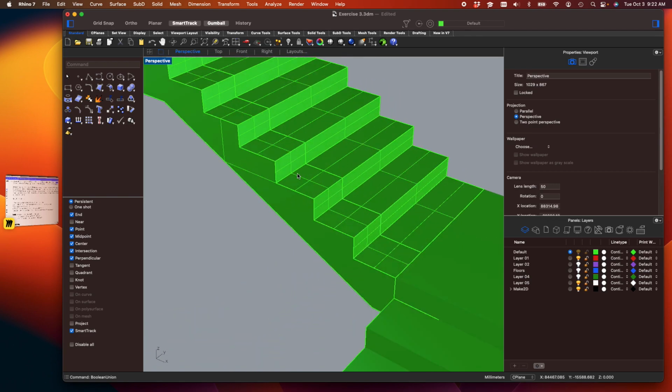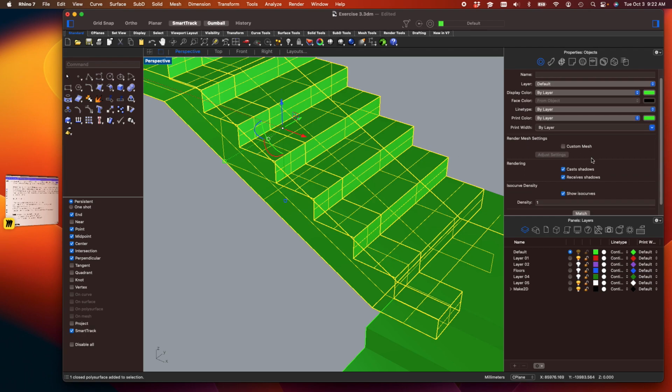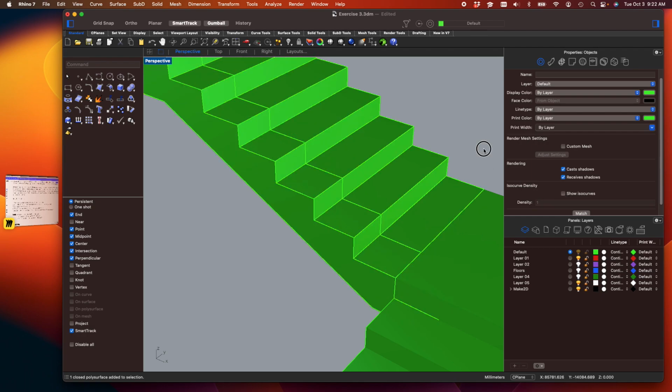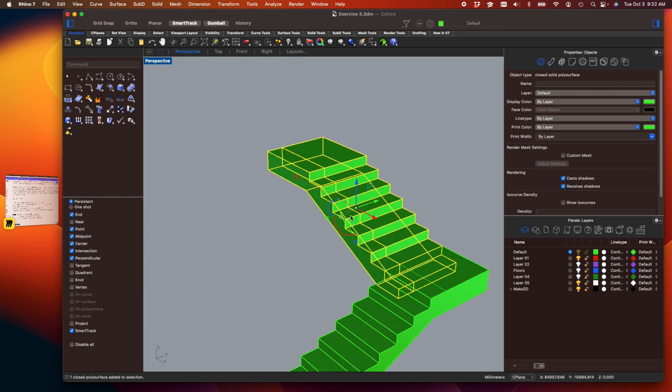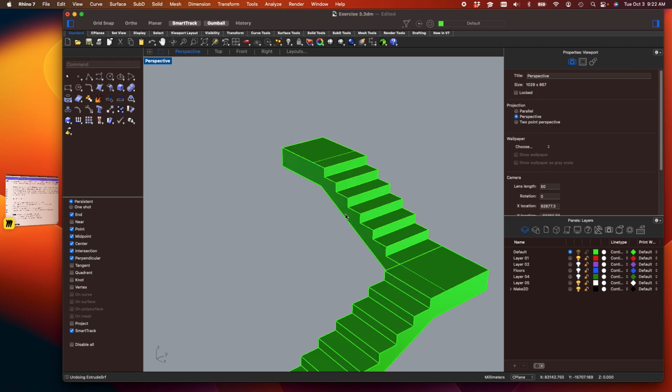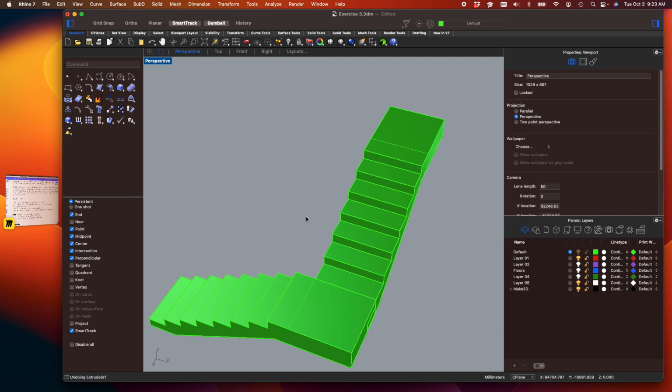And it's going to put those two together. However, I still got all of these lines in here, right? So another option that I can do is when I click on it, you'll see this tab that says show ISO curves. So unclick that, and a lot better, right? Some of you guys, I noticed in the Make 2D, you're sitting there deleting the rest of the lines. So make sure you turn off ISO curves before you make 2D. However, long story short, there is really no way to get rid of that line that's there. So be careful what kind of method you use when you make that piece longer, or just keep in mind when you extrude it. However, the good news is in rendered view, they all disappear anyway. So the object is nice and flush.